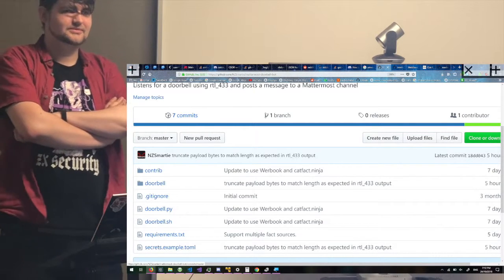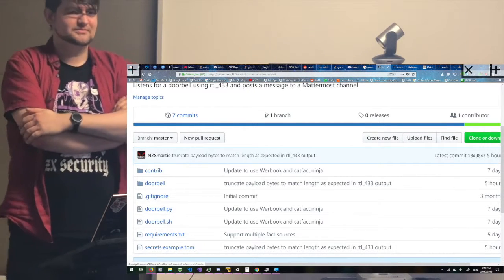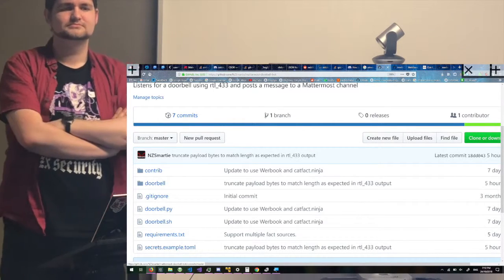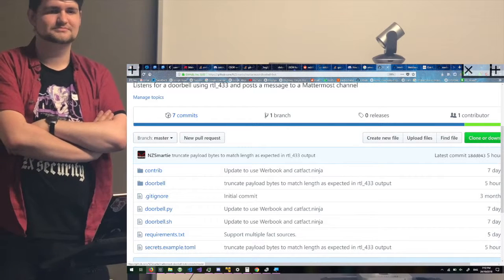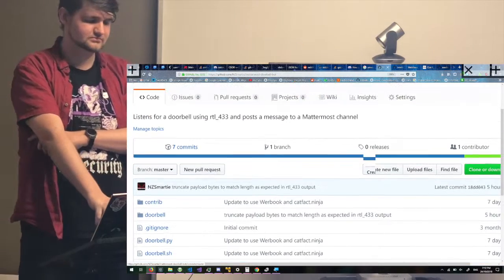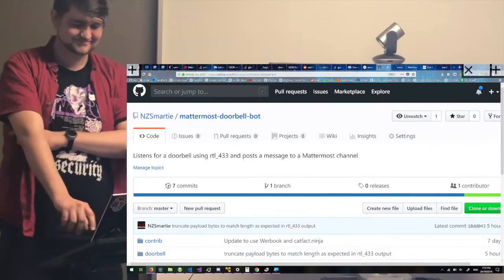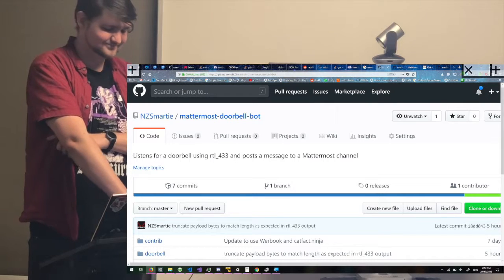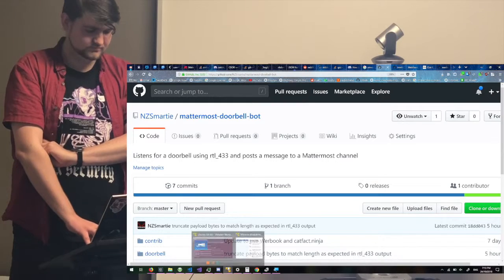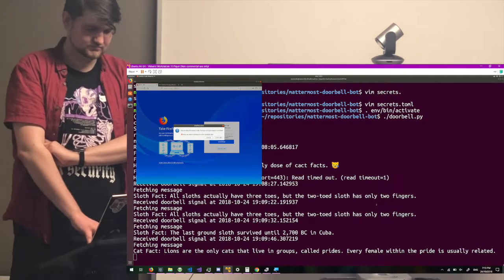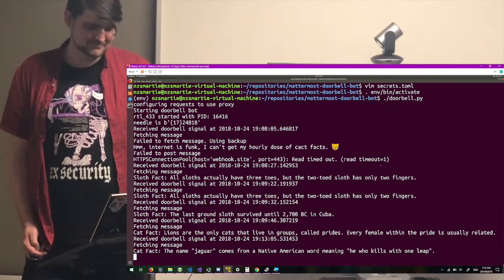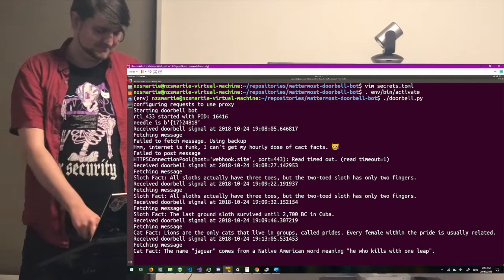You can get one in a nice little USB form factor with Wi-Fi control. And it has a separate microcontroller for the 433 radio that you can flash an extended firmware that'll let you do raw dumps. It's great. What is it? It's an ESP8266. There's a theme here. A 50 cent RF 433 receiver and transmitter in a nice little form factor with a bi-volt converter, so it takes micro USB. And it also has an EFM8 microcontroller specifically for doing the RF component.